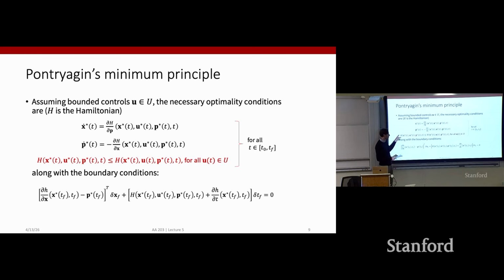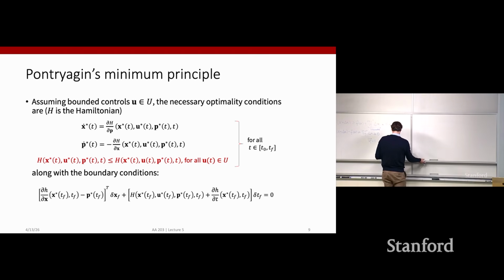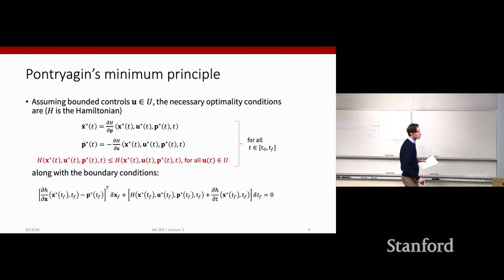The bottom line is that obviously this is complicating things, because before it was just enforcing an algebraic equation where we would express u as a function of x and p, and then doing the substitution. Now we will basically have to solve an optimization problem and derive a solution of u as a function of x and p, and then do the substitution again. So mechanically, it doesn't change much. It's just more complex because before it was enforcing an algebraic equation. Now it's solving an optimization problem.